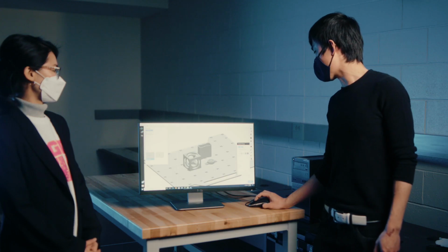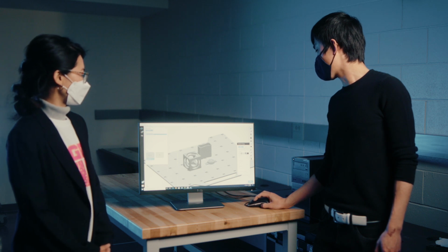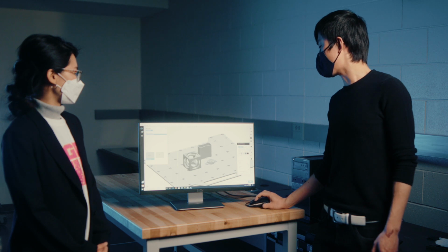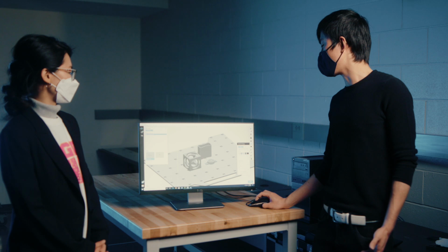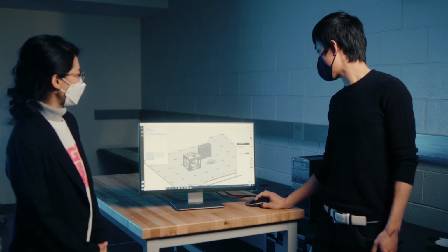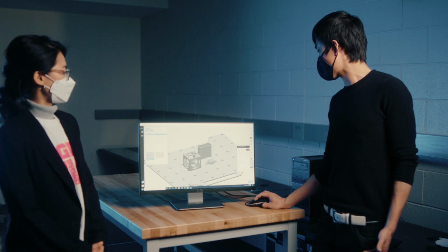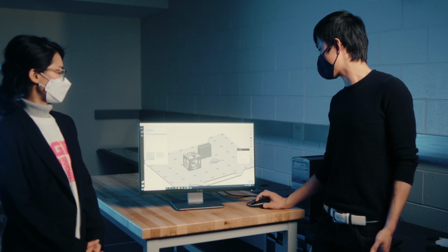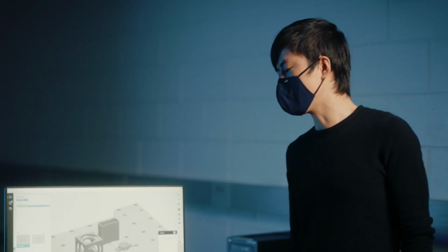And then for the model setting, we want a high density for this model, but we don't need to go full solid, because the bearing doesn't apply much force when we test the part. And then for the support material, we go with the same smart style, and the arrangement just sitting here is fine. Now the orientation for this part is very important.